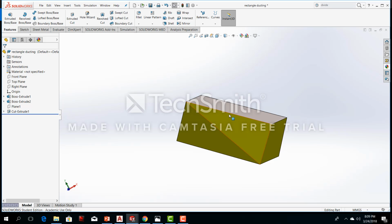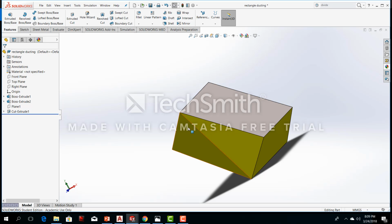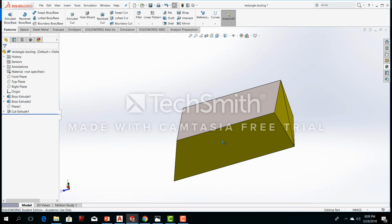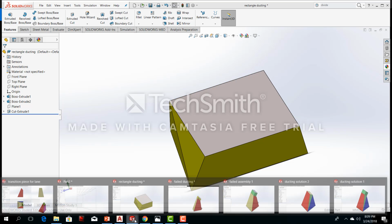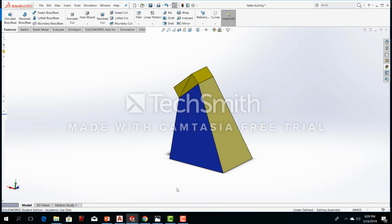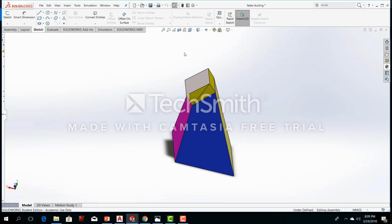So these lines here are parallel to each other, so both surfaces will be parallel. Okay, and I've used triangulation then to bring those back up to our ducting. And I'll show you then how this is assembled. So this is actually assembled just like so, and our rectangular ducting would slide into place here.